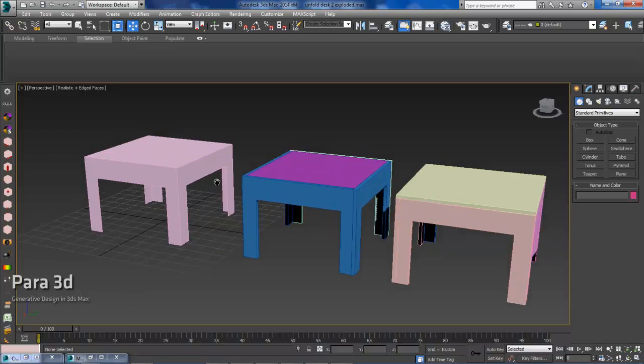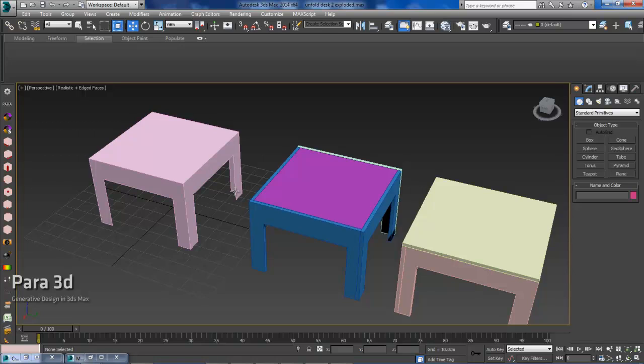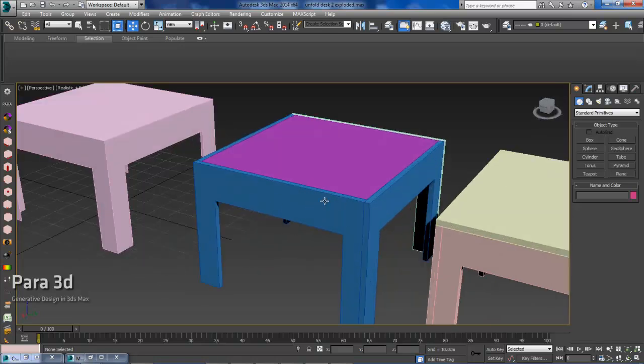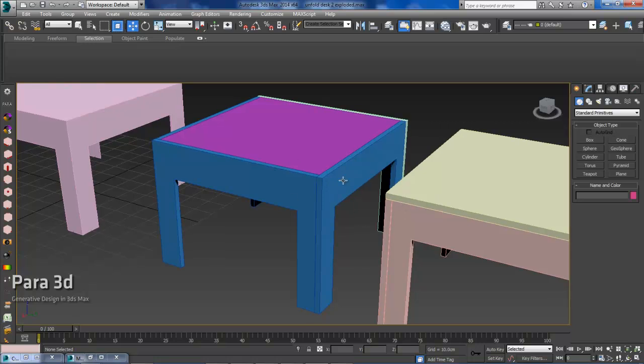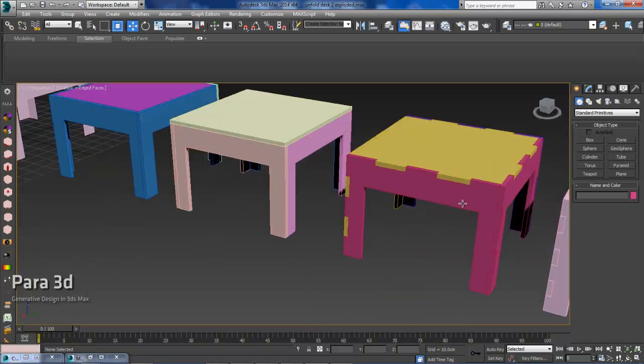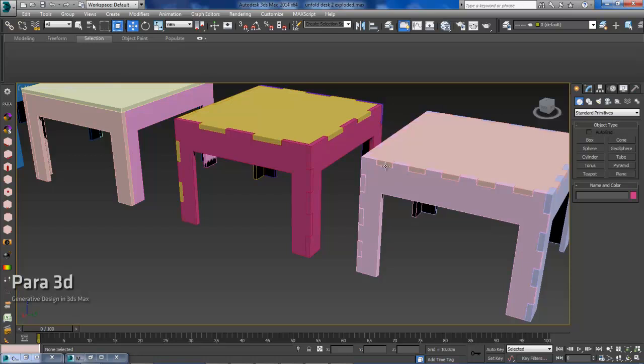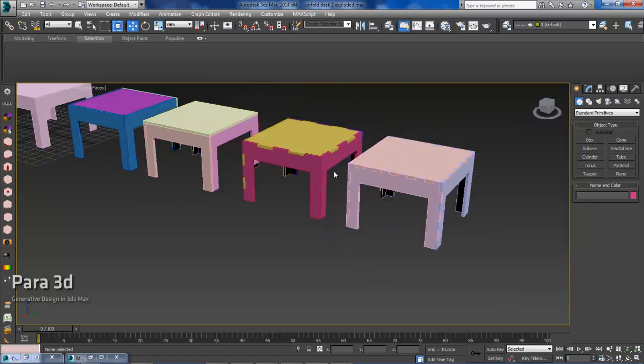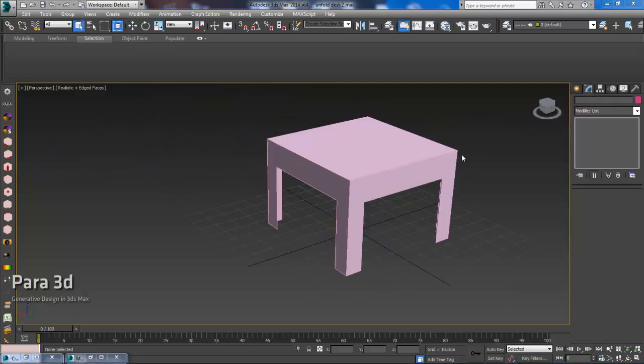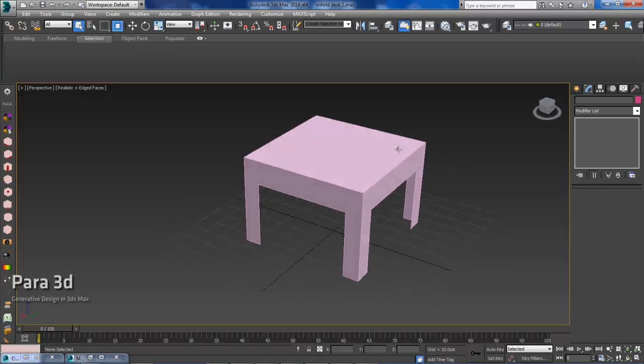For the tutorial, we are going to show you how to add material thickness to a geometry, and then go over a series of different joint types. Here is a butt joint. We're going to show you how to reverse those butt joints. This is a box joint, and then we'll also give you the option of changing the dimensions or dealing with joints specifically with numbers. Okay, we are going to go over the details of the Disassemble tool.